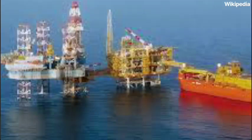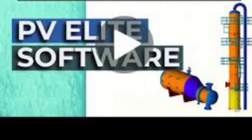So wind load, that calculation, it's okay. Wind load calculation comes from their input. It's not by mechanical. So they give the speed and the maximum per hour rate, and they give some factors. So these are the factors to be considered in our calculation, and that factor and that speed we have to put in our PVLite calculation and execute.